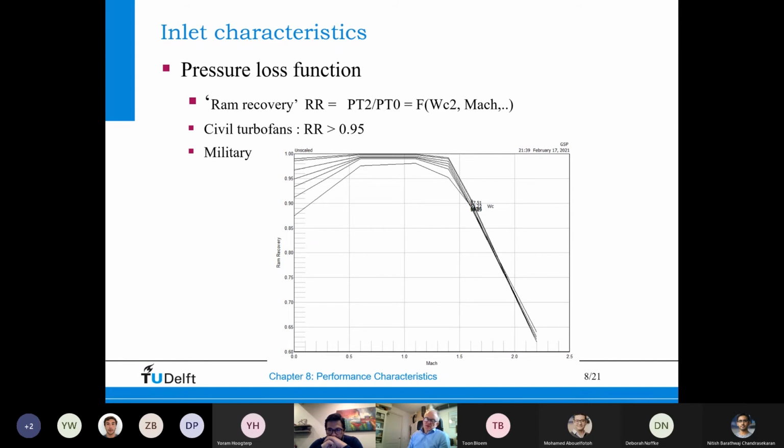But a sharp inlet lip is not very efficient at standstill. And it's probably also smaller, so the cross area of the inlet is reduced to also allow supersonic efficiency. If you made it as big as with the same design rules as for a civil subsonic turbofan engine, it would not work at all supersonically.